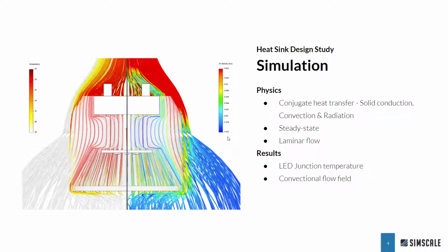Now we're going to be running a steady state simulation and using laminar flow rather than employing a turbulence model. And as I said earlier, the result of interest is really going to be the LED junction temperature as well as a general understanding of the convective flow field.